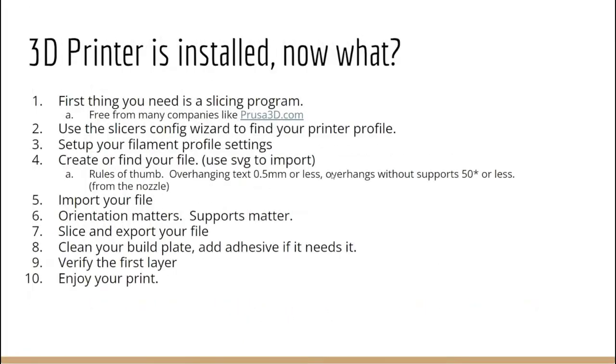We'll go over some of the slicer's configuration wizards because in order to use your printer, depending on the slicer that you have, there are certain parameters. Not every printer is built the same size. They're not all the same in how the printer head moves. It could be something called a core XY, where the bed moves down, or it could be what they call a bed slinger or Cartesian printer, where the bed's moving in and out, and then the nozzle's moving left and right. So it's important that your file gives the correct instructions to the printer that you're using.